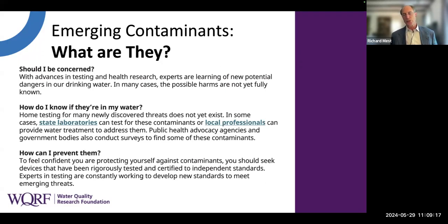And we're very accustomed to using measurements in grains per gallon or milligrams per liter, parts per million. And then we were introduced to parts per billion because analytical instruments could test finer particles, finer size contaminants. A part per million to a part per billion is 1,000 times different, to give you a perspective. We now test in the parts per trillion, which is 1,000 times smaller than a part per billion.